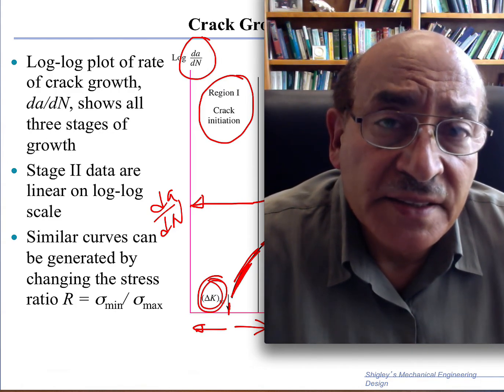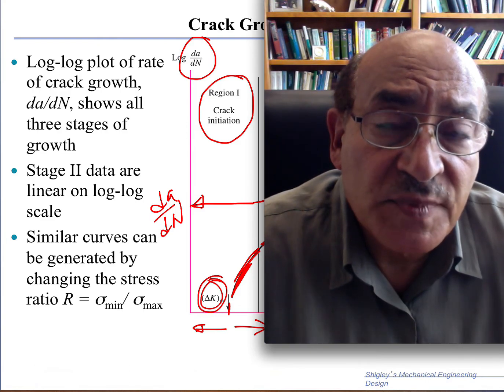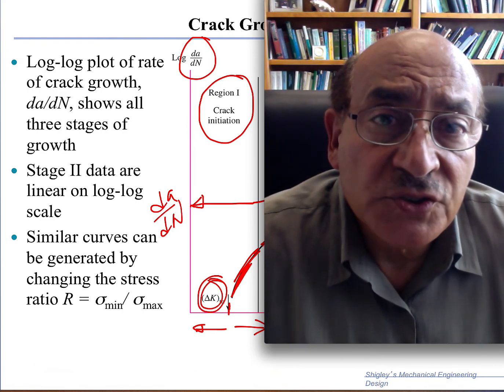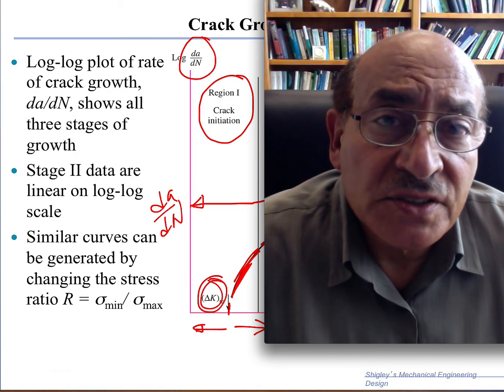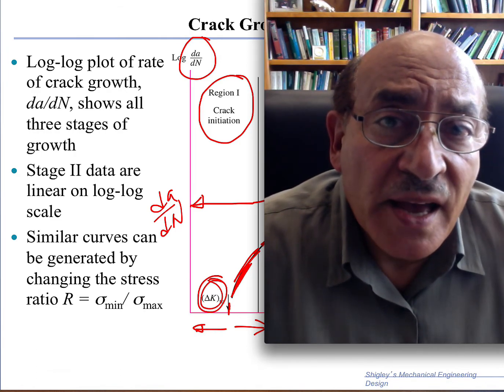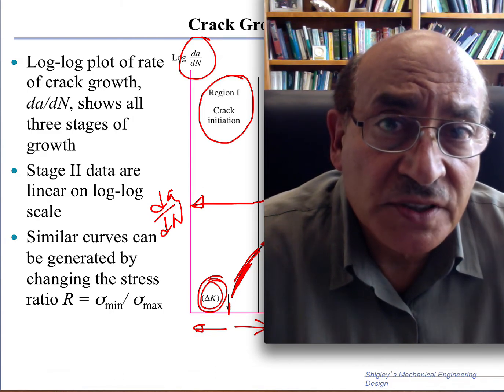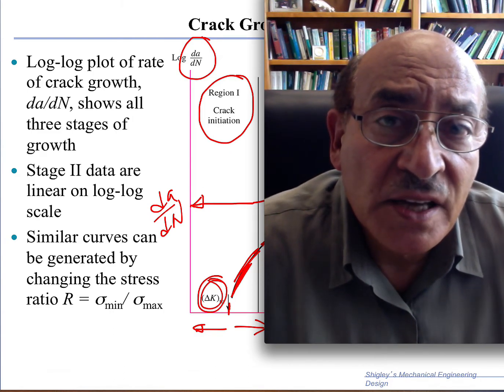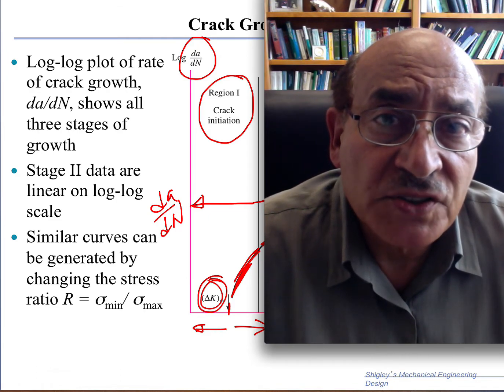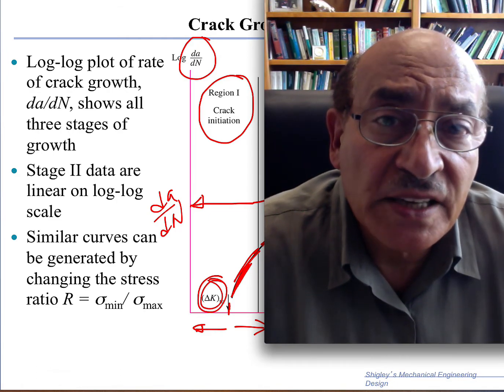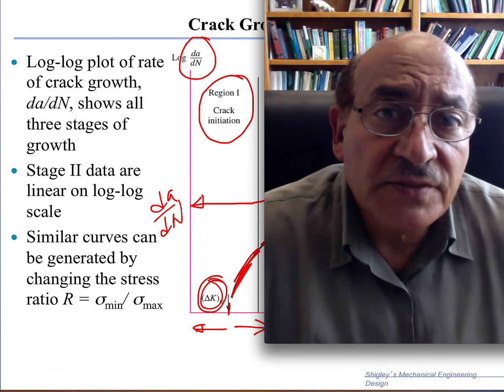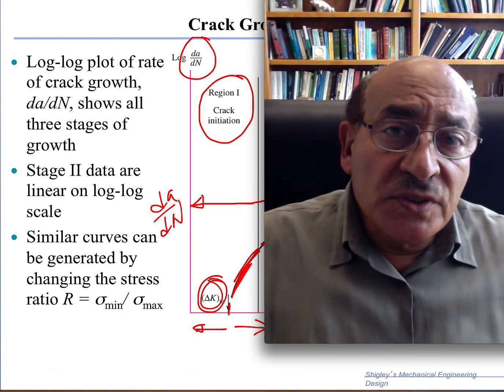And then I integrate this function with respect to N to determine how large the crack is going to grow. And when the crack goes to a certain critical value, then I will be able to say that the structure has reached its limit, and then we get failure. So this is the procedure that we will pursue.